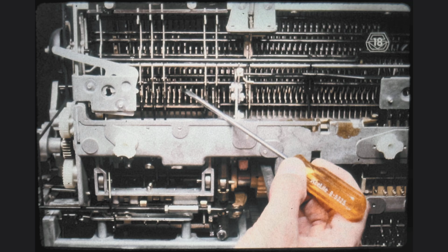With the aid of a screwdriver, we can push the individual interposer towards the front of the machine, in the same way the filter shaft does it. Be careful to exert only rear-to-front force on the interposer, so as not to strain the interposer latch spring. The interposer will thus come out of engagement with the compensator tube and also out of its latch-down position. In short, it will return to its rest position under the action of its own restoring spring after we cause it to become disengaged from the interposer latch spring.